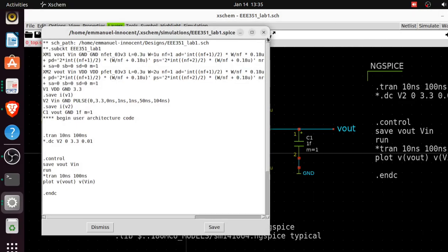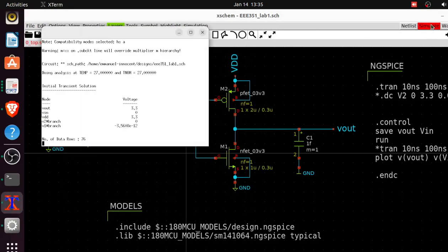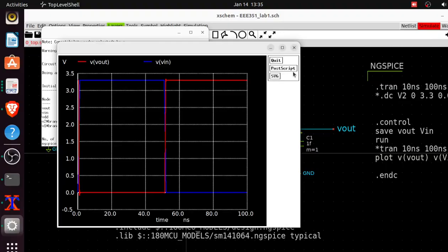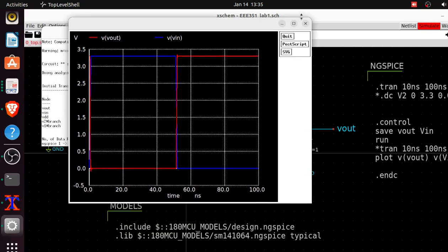Okay, netlist, no error. You can see femto looks like the ideal case. So now you can see how output capacitance can cause propagation delay, and how it can affect the performance of the CMOS inverter gates.